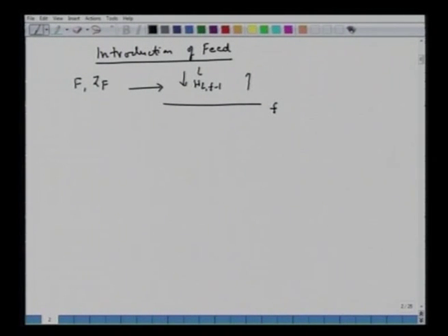Then we have the vapor with enthalpy HG, F, originating from the feed plate, and here we have L bar. Notice this change in the molar flow rate because of the feed introduced: L bar with enthalpy HL, F, and the vapor which arrives with molar flow rate G bar and specific enthalpy HG, F plus 1.